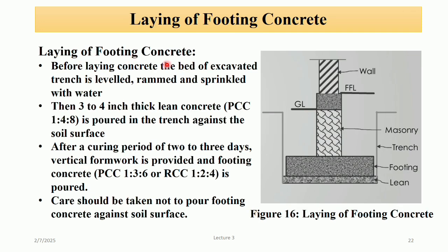Laying of footing concrete. You can see in this figure it is a trench, and this is the bed of the excavated trench. First of all we level the bed, then we ram. By ram we mean we compact the bed with sprinkled water. After that, we provide 3 to 4 inch thick lean concrete.